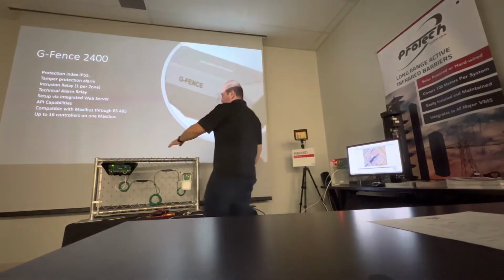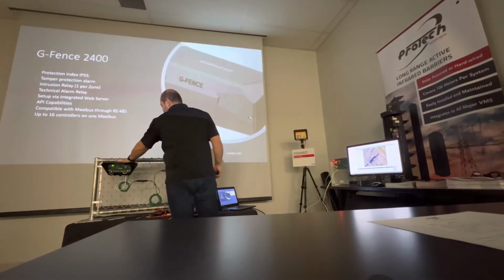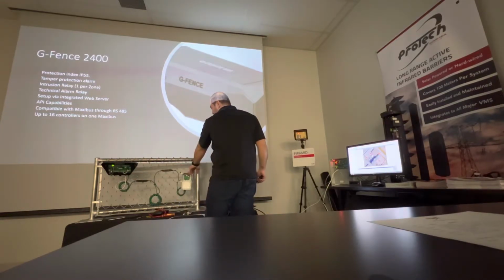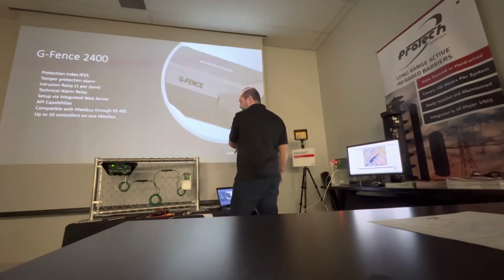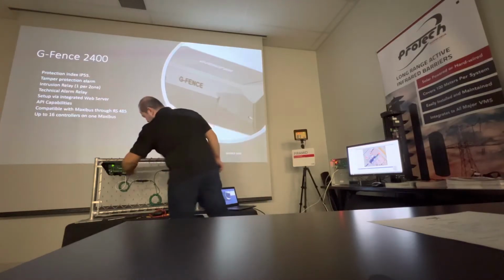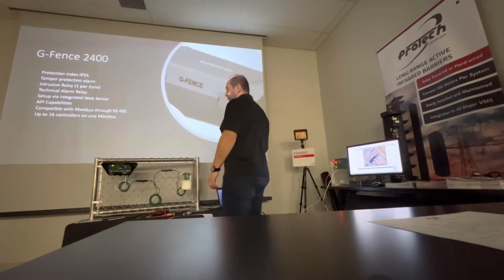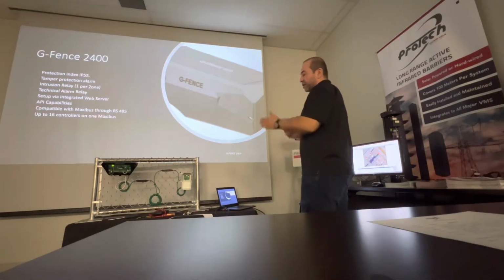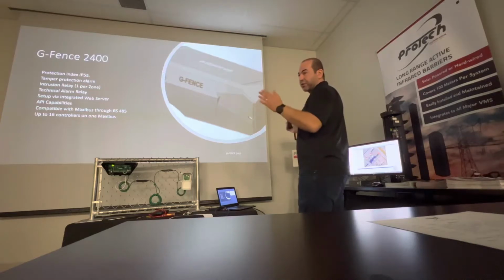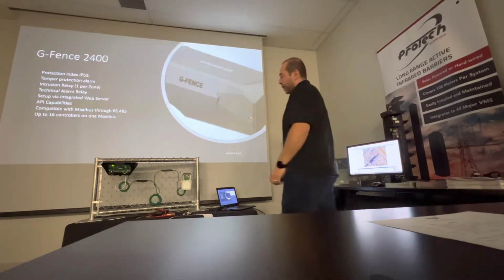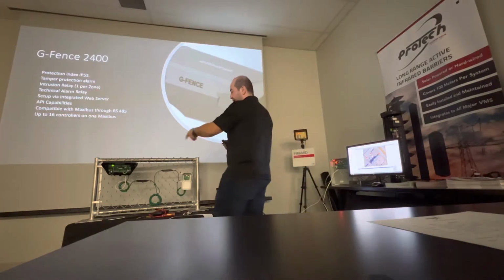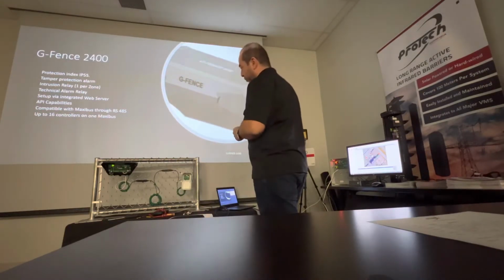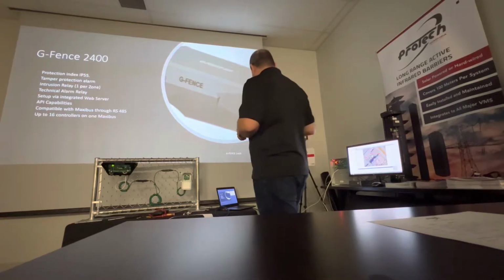So in that case, use a control unit up to 600 meters, so 300 meters, link it together with the link box up to the termination link, and you do the same step if you need with 300 more meters. So in that case, you will have 600 meters total independent system, and if you need more than that, you can tie together another equipment for 2400 together to be able to communicate with the Maxibus.